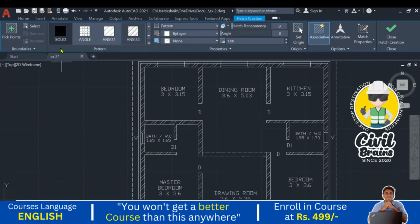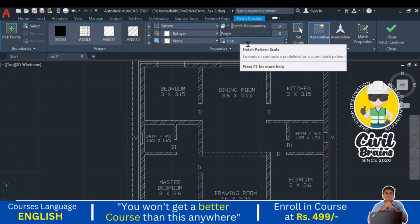So just go to the hatch. So here you can see this one. There is a scale. This is a scale. So if you change the scale, the hatch will change. I will just show you. If I want a closer hatch, again I just take 0.5 and I just press enter.